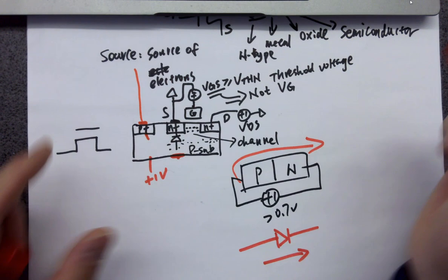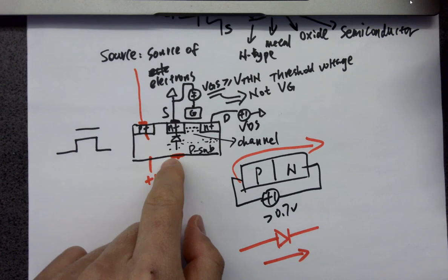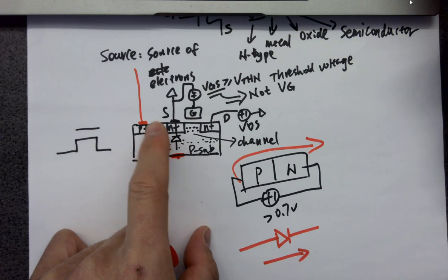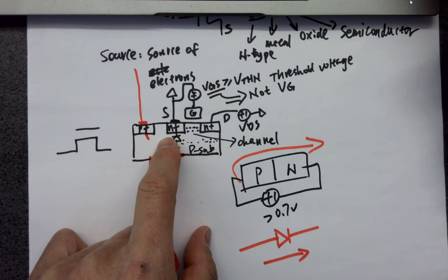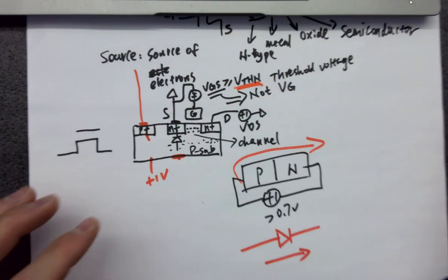Just connect to the top, bottom up, using via 1, via 2, via 3, and to connect to metal 3, and you have an opening on the top of the chip, and you short it to ground. So in that case, you can ground your P-sub, which is critical. So you are not having any forward biased diodes. So you can keep your threshold voltage in a reasonable range.